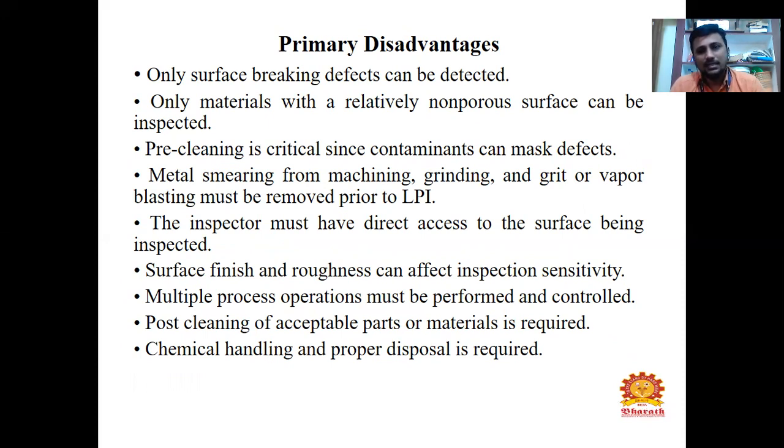The third major disadvantage is that pre-cleaning is critical since contaminants can mask defects. The fourth major disadvantage is that metal smearing from machining, grinding, and grit or vapor blasting must be removed prior to liquid penetrant inspection. The inspector must have direct access to the surface being inspected.